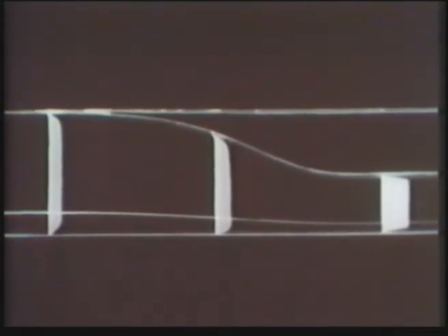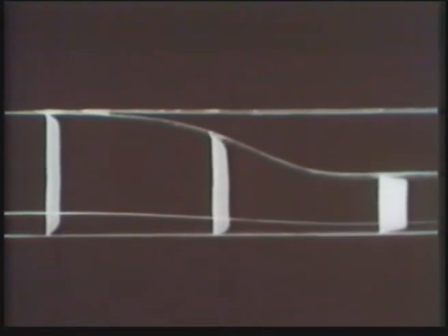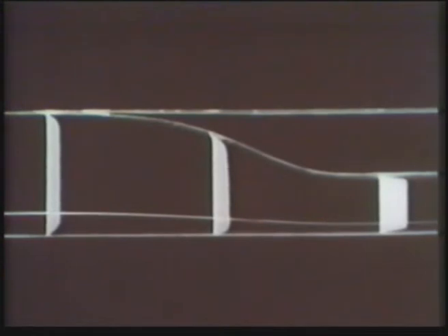After the contraction, the boundary layer is thinner. Note that the distance from the wall to the streamline downstream is about half what it is upstream, because the two-dimensional flow contracts 2 to 1.